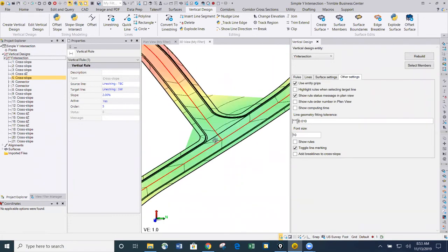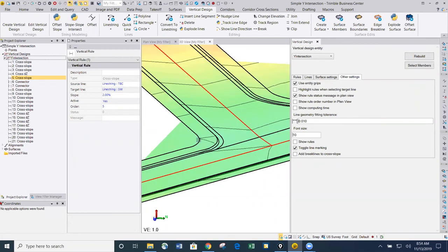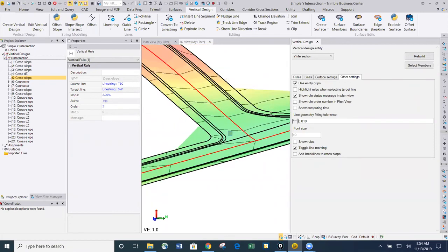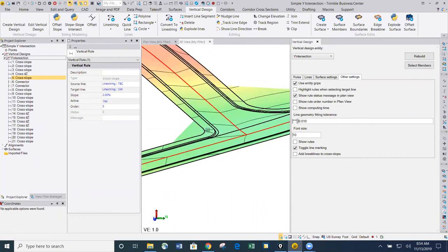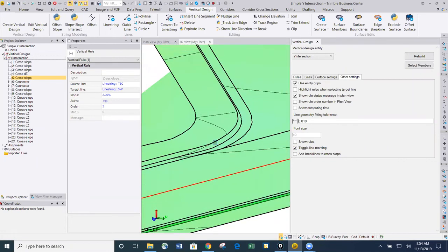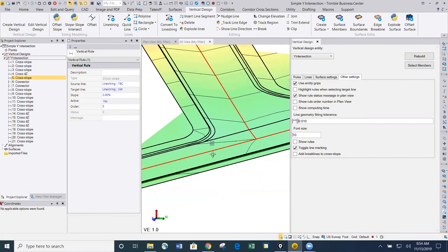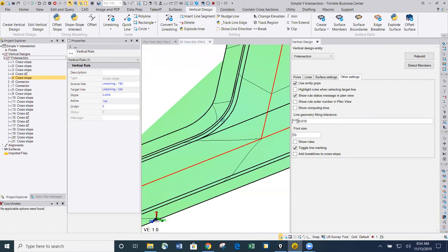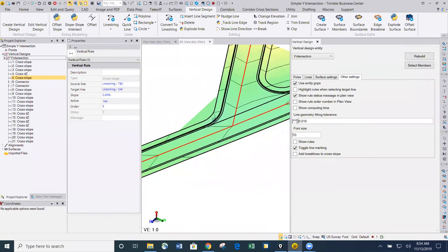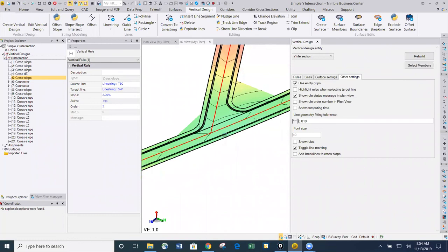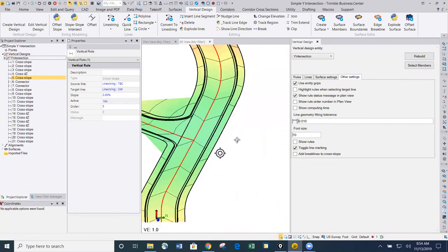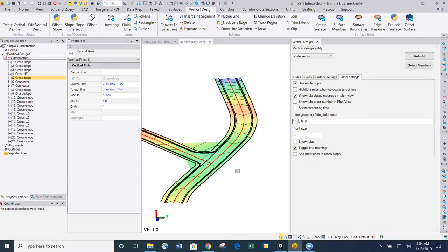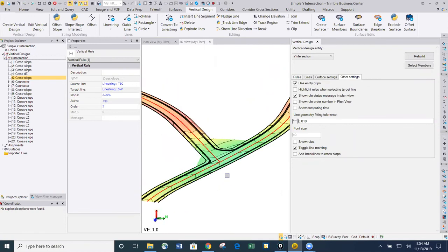And you can start doing your subgrade adjustments if you need to by just dropping subgrades in on this surface like you would do normally, or by doing things like offset lines, offset slopes. And in 5.2, there's some really nice string modeling tools to do some offsets using pairs of strings, and you can extend the slopes or calculate intersections of two pairs of strings and things like that. So some additional tools in here, along with side slope and corridors, to build out relatively complex three-dimensional site subdivision type models.